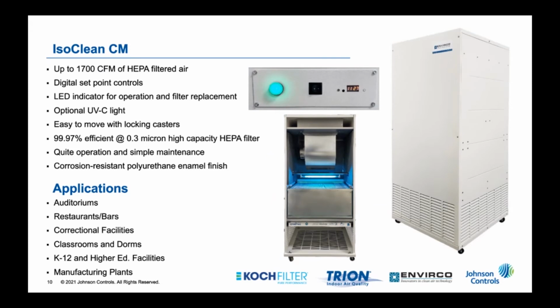So if you go to the next slide, we'll get a glimpse of the CM and what it looks like on the inside. The IsoClean CM is a highly serviceable unit. The controls are readily accessible on the left side of the unit. You've got a big indicator light, which will turn red if the filter loads up. Typically that means that the pre-filter has loaded. So if you change the pre-filter, redeploy the unit, and the light turns green, you're good to go.